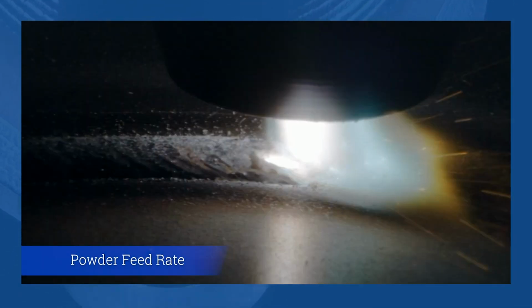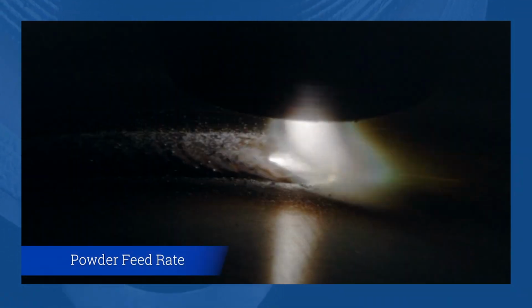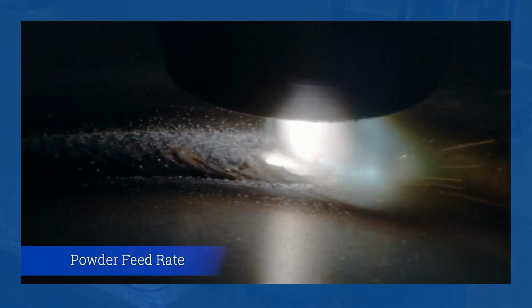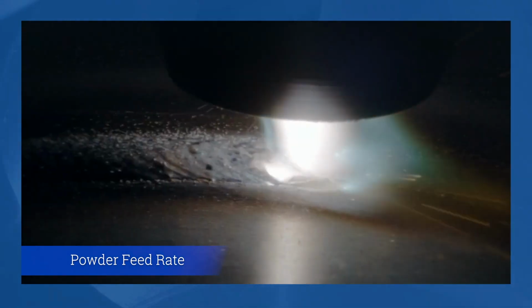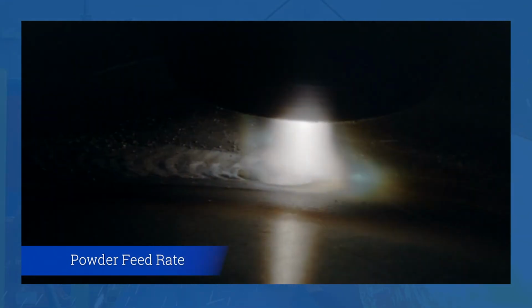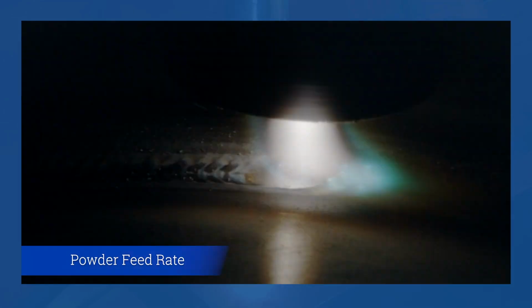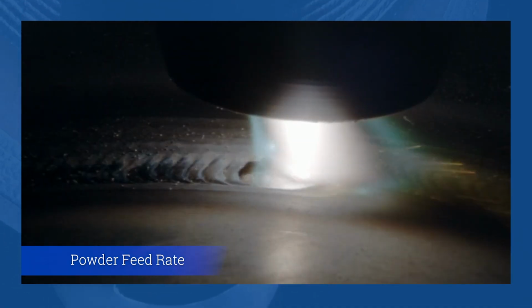Let's talk about filler metal deposition rate. In this case, we're using powder. Here, everything's set properly, and we're going to turn it up too high. That's still an acceptable weld. You may want that level of volume, but now we're going to turn it down, and it's pretty obvious when you don't have sufficient powder. You see the divot right where the arc is impinging on the workpiece? Tremendous dilution and an underfilled part.